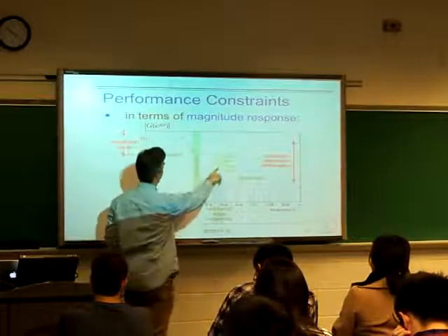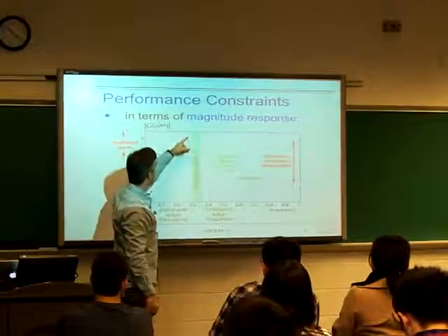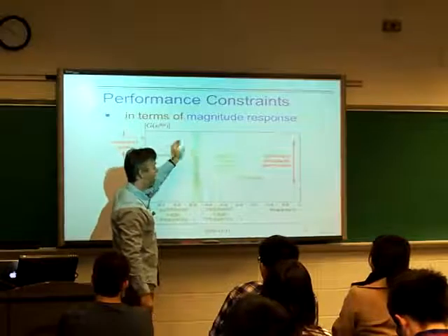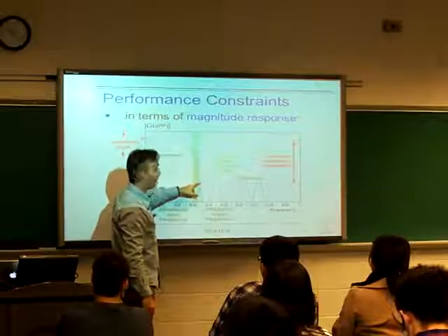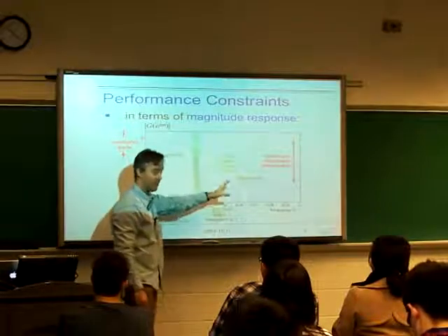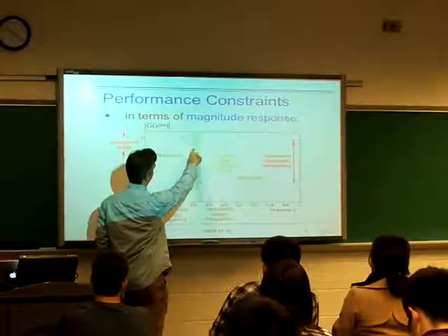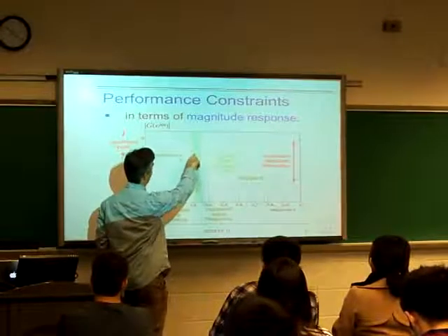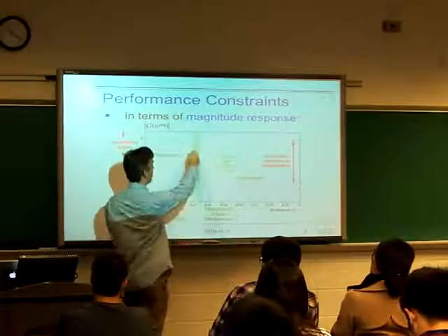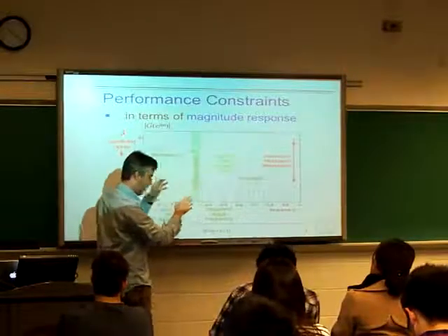It says here that the optimal filter will touch here and here. That is, it'll be at the very lowest range of its pass band, just at the very highest frequency in the pass band. It'll be the largest value allowable in the stop band at the lowest frequency in the stop band for this low pass filter. And that's because if it was not quite touching there, then it would mean there was a cheaper, less well-performing filter that would touch there.